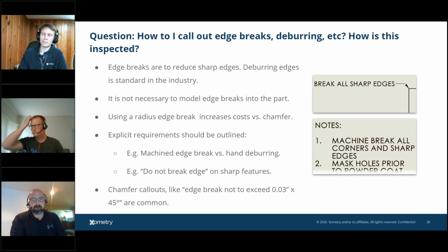Absolutely. Most of the time, the question is almost reversed. For example, we deburr all parts because we don't want you to pick your part up and cut your hand open. Sometimes that deburring is done via CAM, a finishing pass on the part to help remove burrs around the corners. Sometimes it's done with a manual deburring tool, a little tool with a curved blade that you run around your part to remove some of these excess burrs.